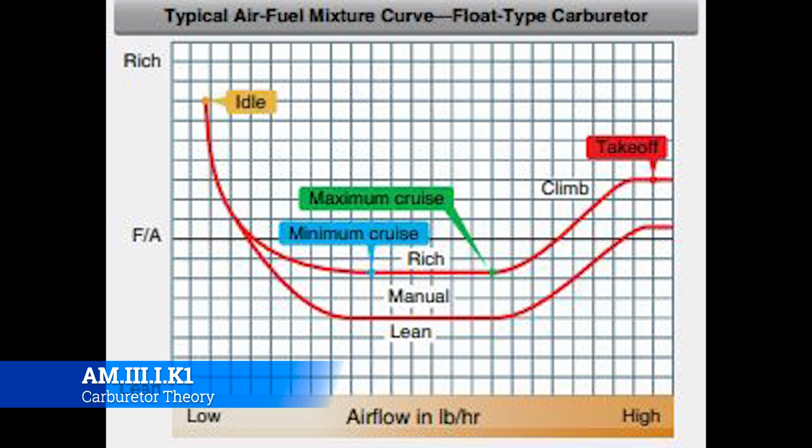Now, when you crank an aircraft, one of the first things you're going to do is put the mixture into the full rich position, and that's what we see on the far left hand side.